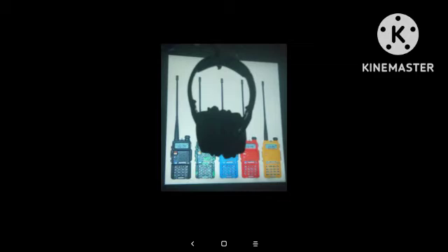Number 39. If you made a half-wavelength dipole antenna for 28.550 MHz, how long would it be? 5.08 meters or 16.62 feet. Number 40. What is a good way to get maximum performance from a Yagi antenna? Optimize the lengths and spacing of the elements.